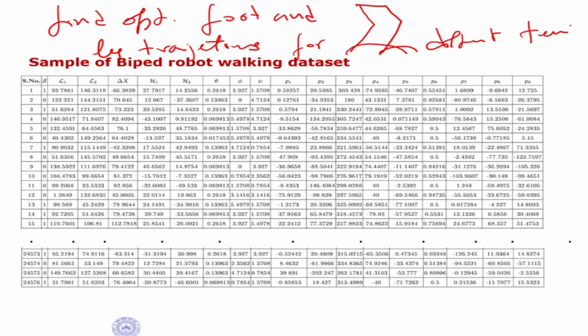For example, if I know that the robot is going up and there is an inclination in the upward direction, I start finding trajectories for different angles. So I take, say, 2 degrees, 4 degrees, 6 degrees, like that. And for each of these, I find trajectories. If it is going down, again the same thing. Okay, alpha is equal to each of these values, find trajectories, and make a database like this. Now this takes a lot, because each optimization will take you minutes, if not hours. And to generate a database like this, covering all kinds of terrain condition, will probably take you days.